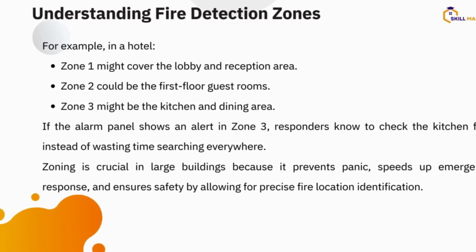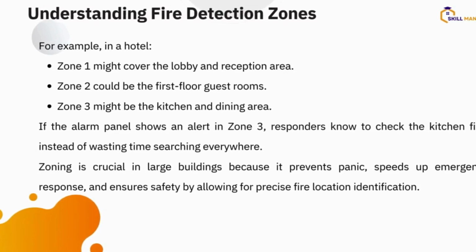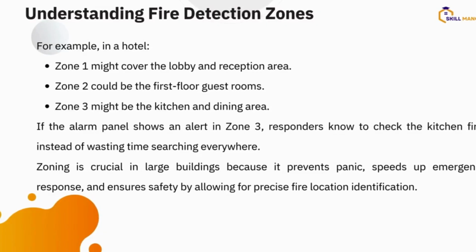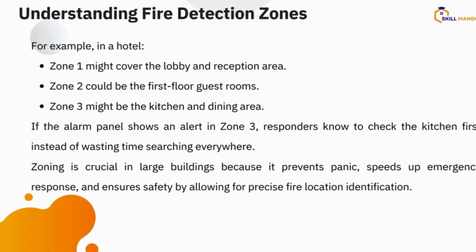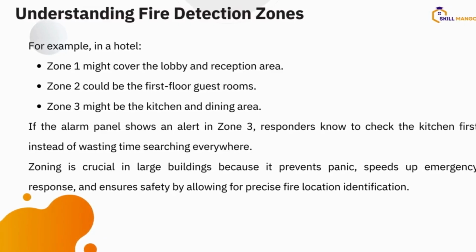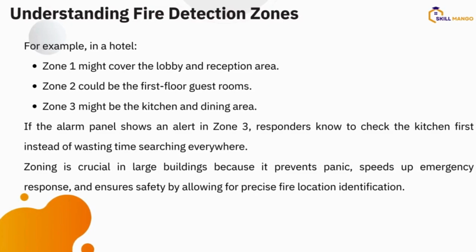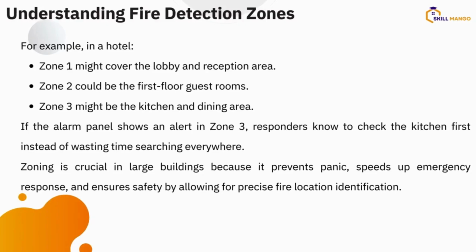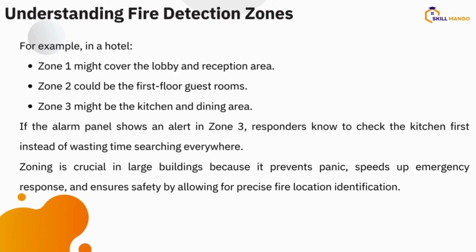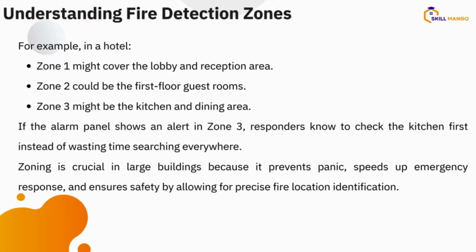So this will advise you the kind of panel you are going to be buying. So when you get to the market, you tell the market person, based on your budget, conventional panel or addressable panel. Oh, I want a conventional panel with four zones, because when I do my zoning of my site, it's four zones or it's three zones, but let me buy four zones in case my client wants to add more zones, more areas in the future. Okay, so this is very important for conventional. It's called zoning. You have to learn to zone.